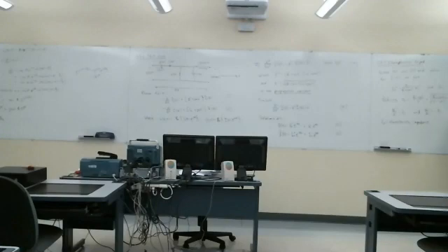And then the capacitance is 67.7 picofarads per meter, and the inductance is 370 nanohenries per meter. Again, in an ideal coaxial cable, both of these would be zero as well.